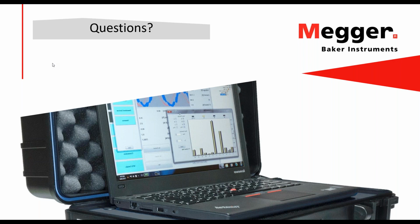We use something called torque signature analysis, which essentially is using the currents and the voltages that are fed into the motor, and doing a Fourier, or a type of Fourier analysis on those currents and voltages, allows us to find all the frequency components of the voltages and currents. So we can find a lot of the problems that you can find with vibration monitoring, but you cannot find all the problems that you can find with vibration monitoring.